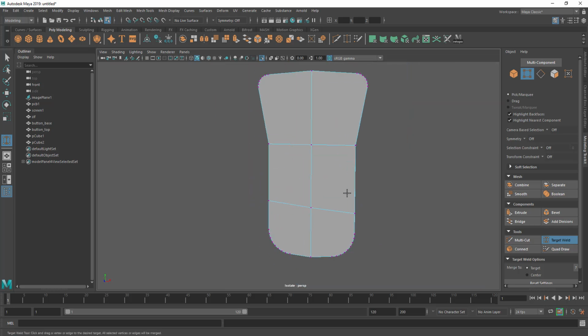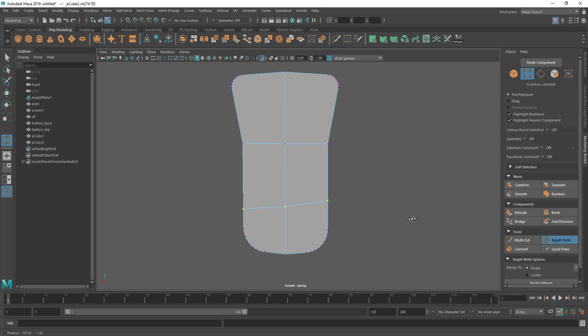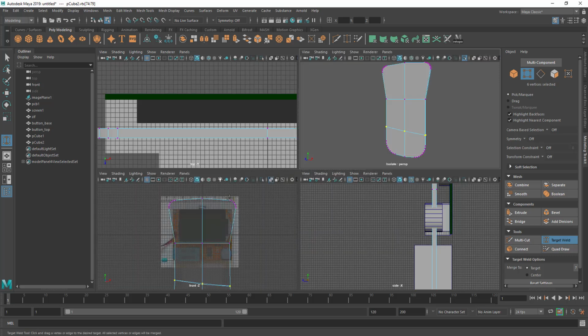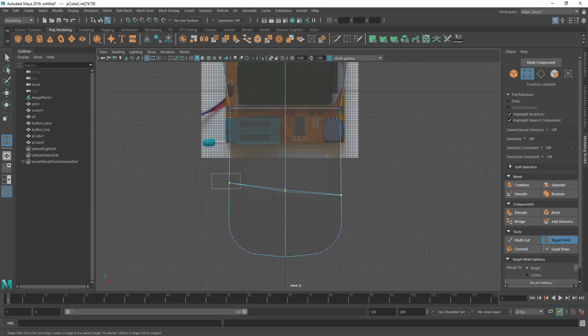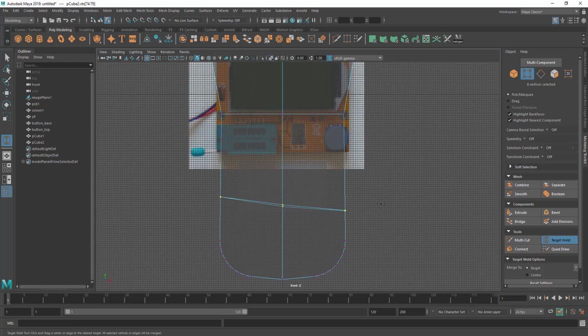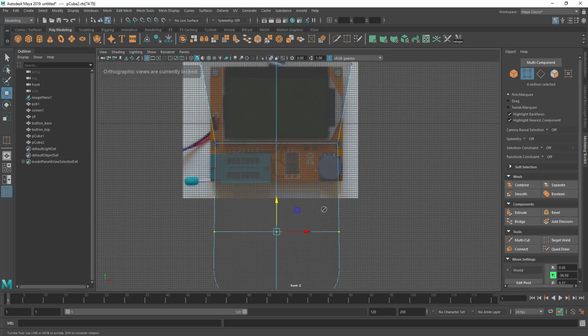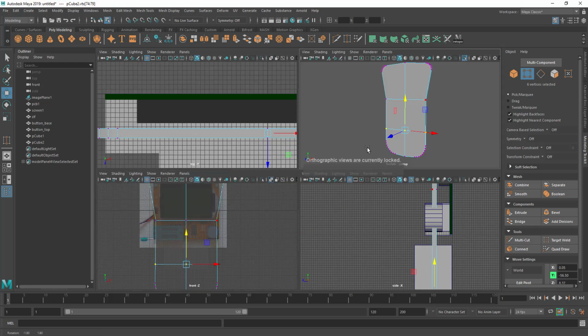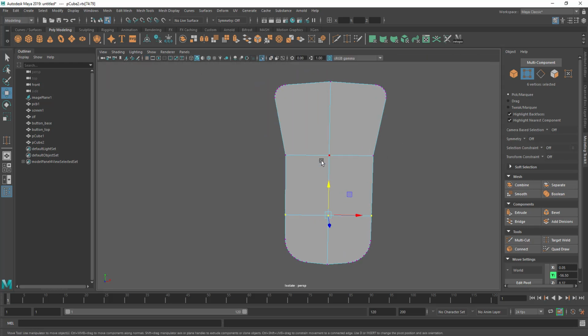Okay, so even though Maya's tools are not on the ball right now, we can still work within the confines of it. So select all the vertex, so I click drag select around. Now you might want to do this in one of the views where you can actually see you haven't selected any extraneous vertex. Hit R and scale downwards. This will straighten the line up, as you can see. Done. Now we have 2 lines to play with for our ergonomic style shape.